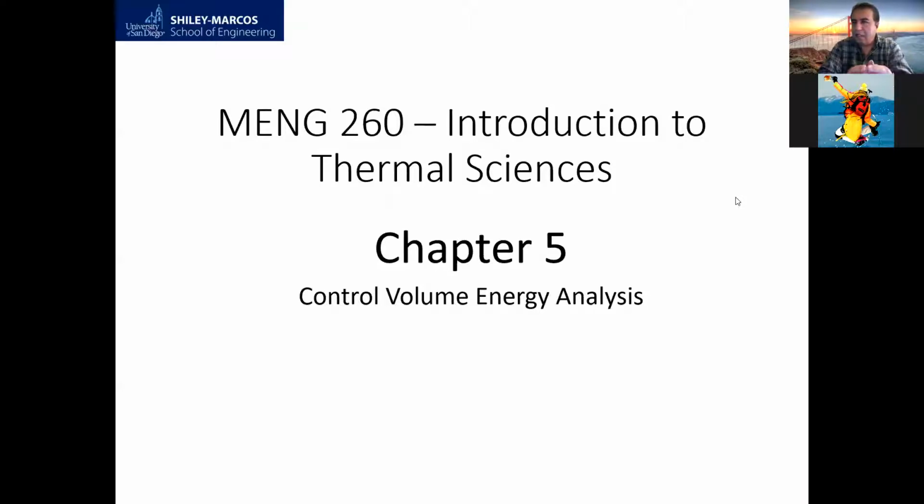Remember that internal energy and enthalpy are the two thermodynamic properties. Always think of enthalpy for an open system, okay? For liquid, try not to use the ideal gas law because it gives you a lot of error. So m dot times delta H, or let me go back a little bit.